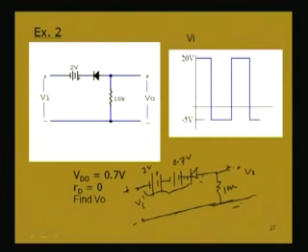In the negative half cycle, when this point is negative, this point is positive, it is forward biasing with a plus 5 volt. So, the potential here is plus 5 volt, and this end point is having minus 2.7. So, this point is having a higher potential, 5 volt, than this point, so it will be conducting. So, in a negative half cycle, what will be this voltage?